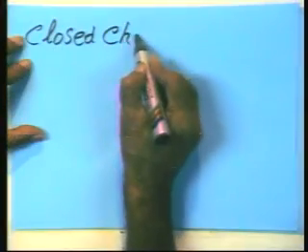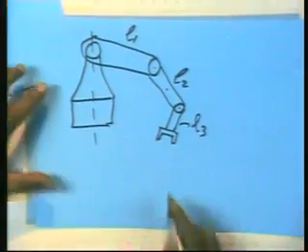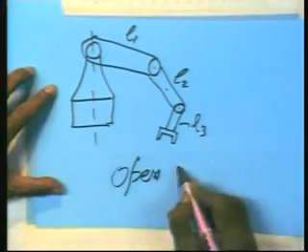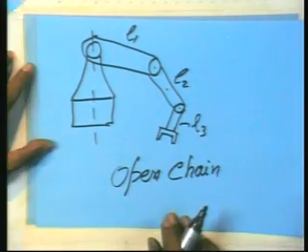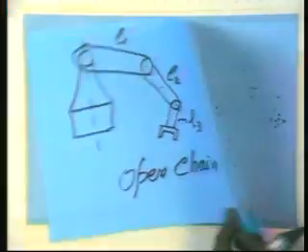Okay, so now having spoken this, let us go ahead with what are known as closed chains. These manipulators with closed chains are becoming quite important in manufacturing in particular. What we call closed chains. You had seen so far the open chains. Here is an example of the open chain. Again, this is a spatial open chain. We had also seen examples of planar open chains. Now we will see what are known as closed chains.